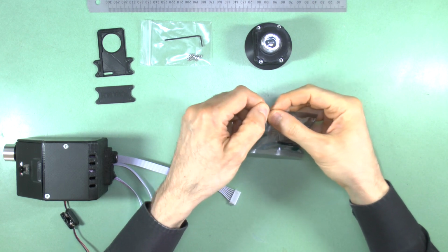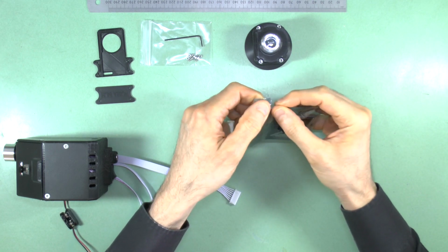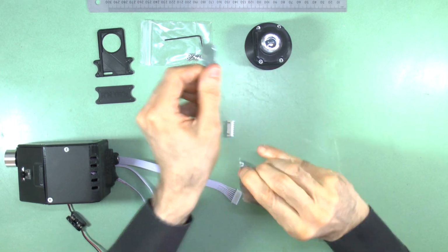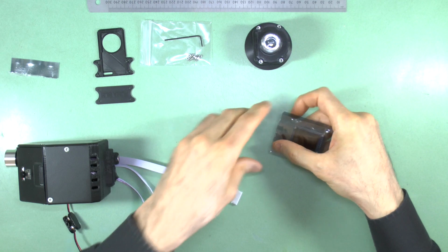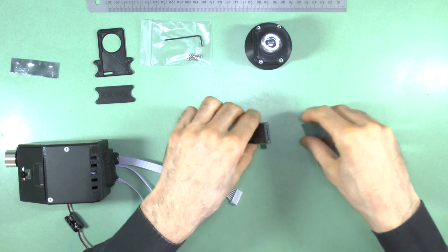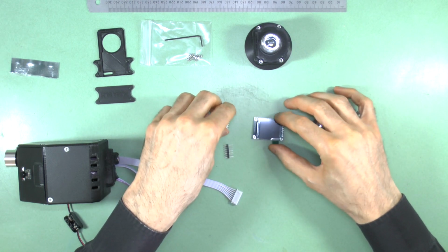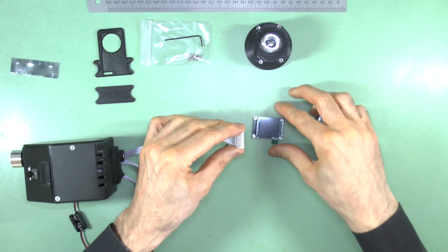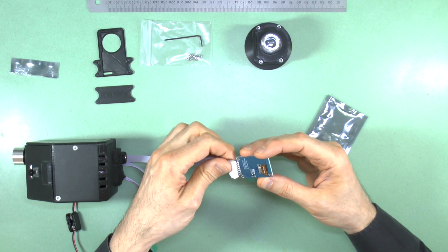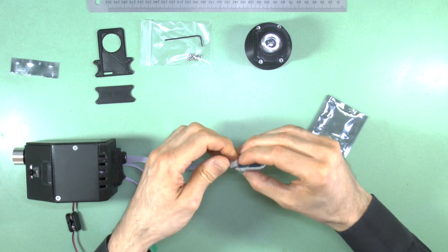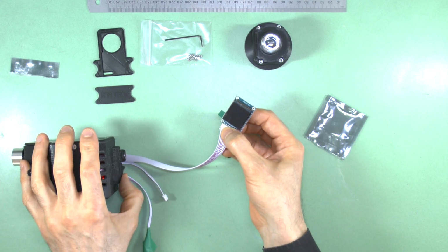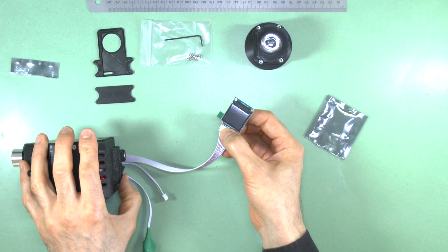Before modifying the TFT screen, first connect it up to a suitable power supply and display driver and test it. Here I'm using the PUMA Control Console or PCC, but you can use your own custom driver. This is so you know that the screen is working and undamaged prior to modification. You should also test the screen at various stages of the procedure to ensure it still works, but make sure you do not perform any aspect of the procedure with the screen still powered on, or you may short-circuit the electronics and destroy the screen that way.